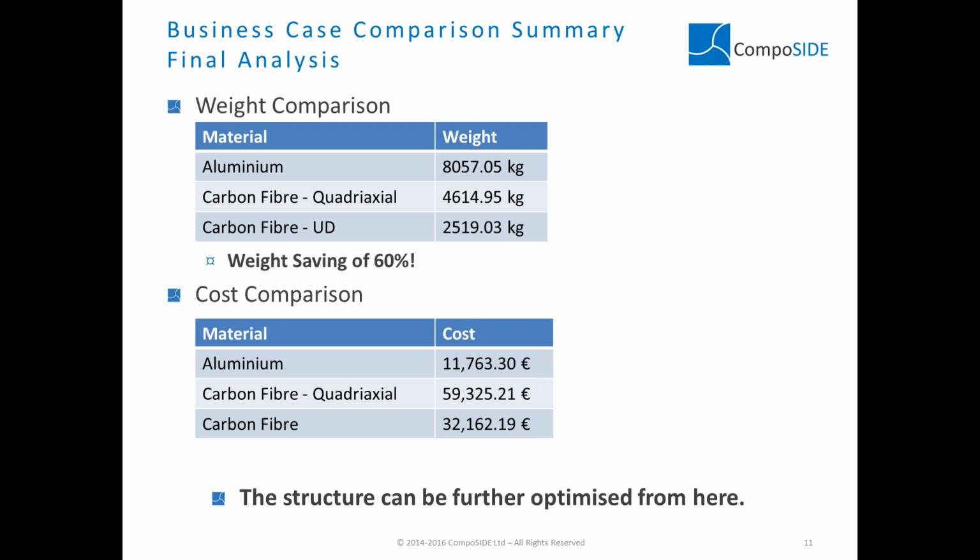So the structural analysis doesn't really stop here. You've still got panels to analyze on top of the structure. We can do this within FE space and do a panel analysis. We can do modal and buckling analysis, or we could check against a different manufacturing process, for example, pultrusion. We could do pre-preg beams. Depending on your manufacturing type and the types of fabrics that you use, we can then go on to optimize.